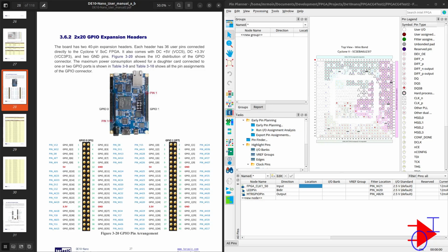right of, so using our Ethernet connection as our reference, right side has the GPIO0, left side has the GPIO1, and what I want to do, or you can say, okay, the one next to the power connection, is use the GPIO0, and it starts from, as you can see, the pin that is closest to the power connector. Pin 1 is that, and then obviously pin 2, and then 3, 4, 5, 6. That's how it goes. And here you can see the odd pins are on one side, even pins are on the other side.